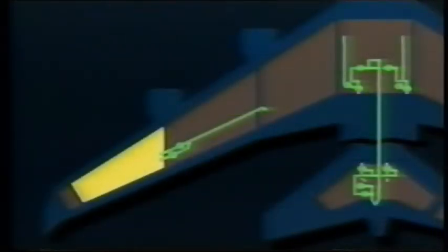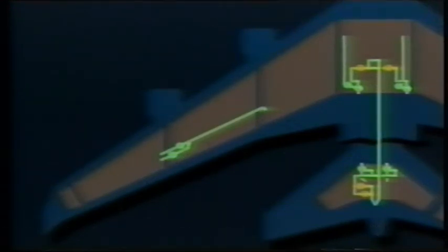Fuel in the reserve tanks and horizontal stabilizer tank transfers to the center wing or main tanks for use by the engines. Fuel from the horizontal stabilizer is transferred to the center wing tank when the level in that tank drops to about 12,000 gallons. At that point, a signal from the fuel system management card opens the isolation valves and starts the 2 transfer pumps in the front spar.